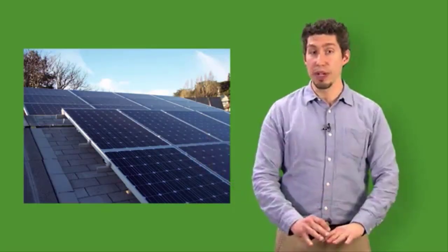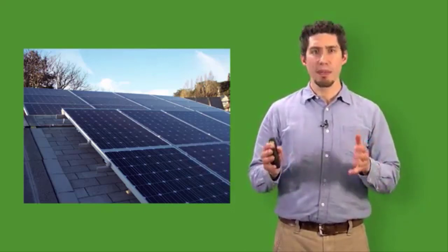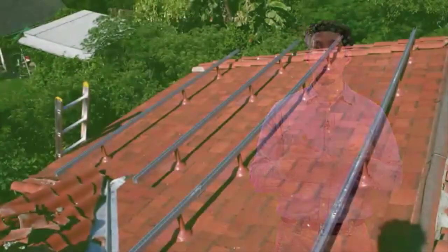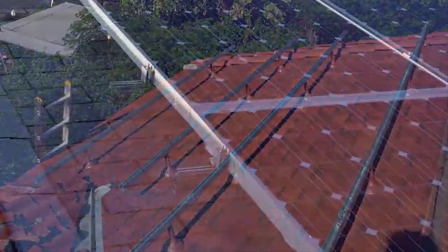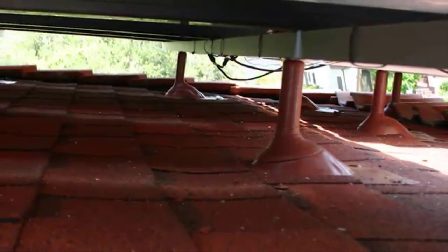Now that we looked at the electrical considerations, let's consider the mechanical components. The mechanical components are what connect the photovoltaic array to the building. There are several commercial manufacturers for these parts, but they all have some degree of compatibility. There are metal racks that connect the photovoltaic panels using specialized clips, and those metal racks are then attached to mounting points. Those mounting points are then connected to a rooftop using lag bolts or clamps. So first we connect the photovoltaic panel to the racks, and then the racks to the roof.